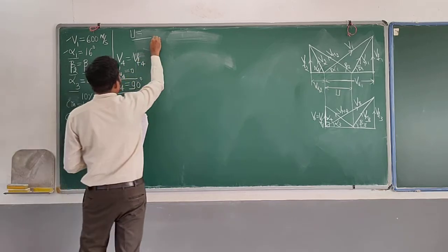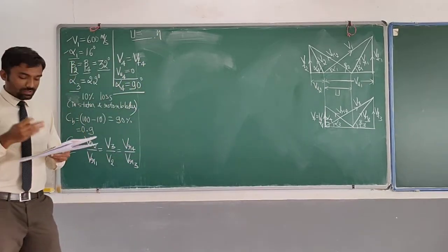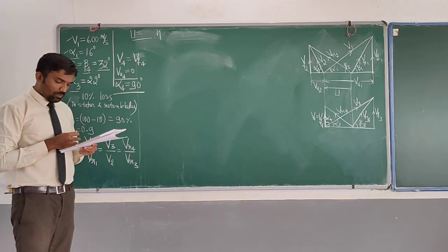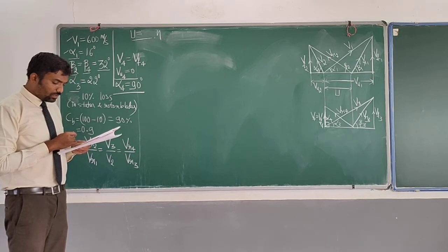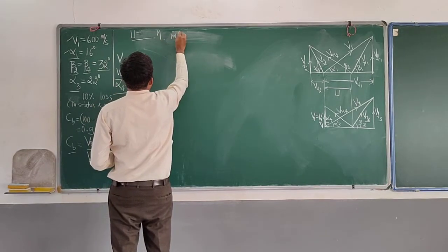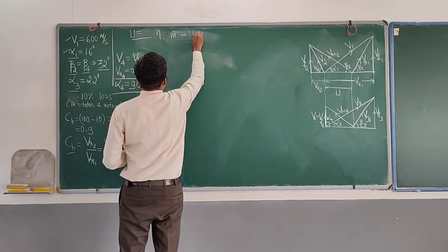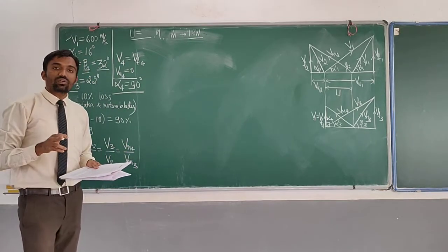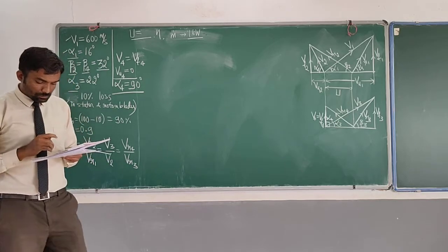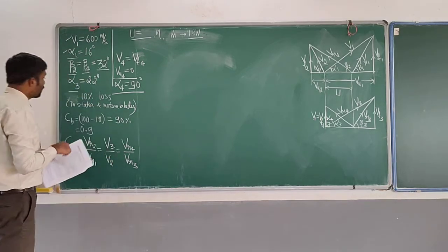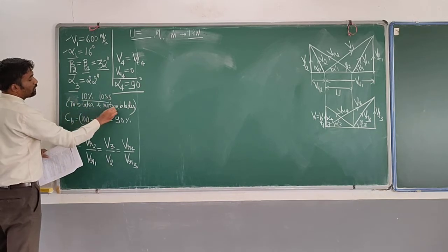Then the rotor efficiency: we have to find the efficiency, that is work done upon the kinetic energy supplied, W upon V1 square by 2. Then we have to find the specific steam consumption. Specific steam consumption means you have to find m dot when the power generated is 1 kilowatt. Assume that 10% loss takes place both in stator and rotor blades.